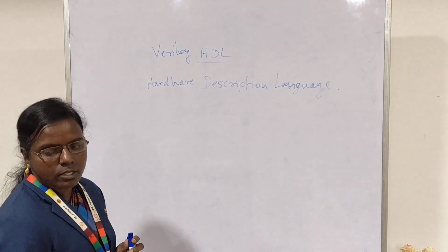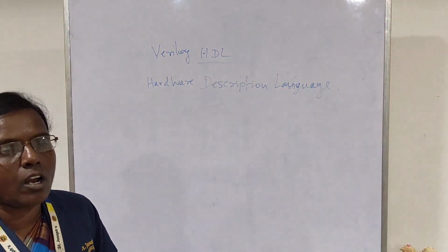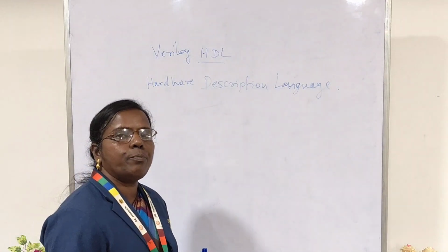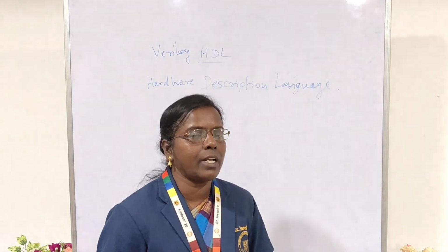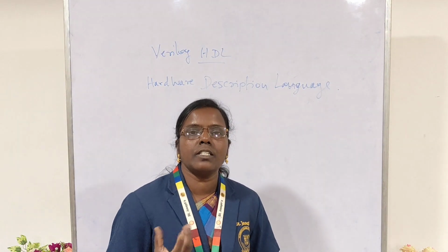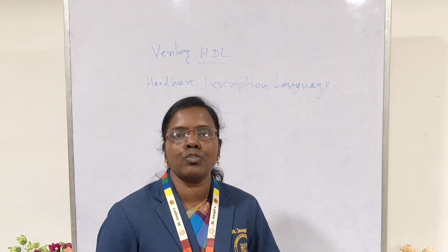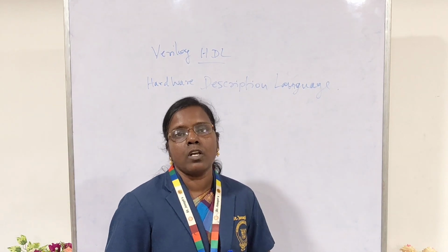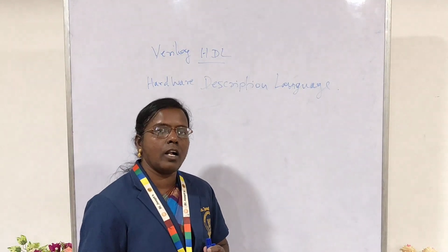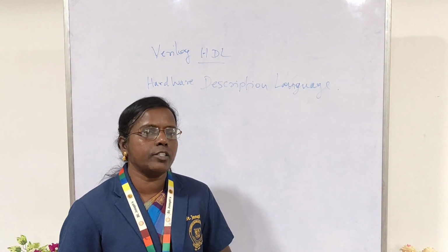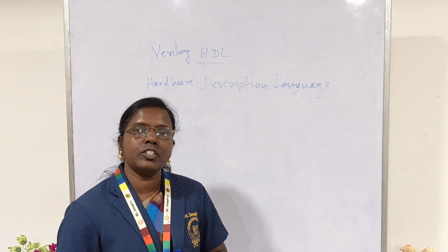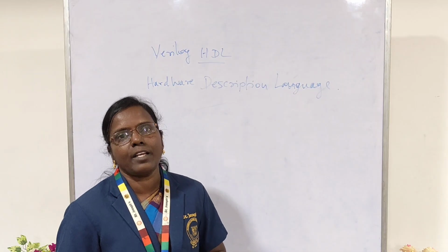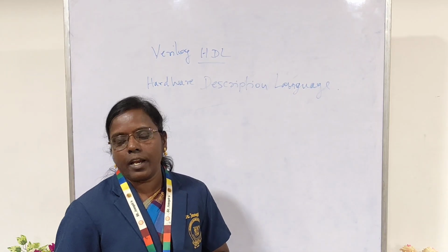Module is the keyword used in Verilog. Verilog has been derived from the C programming language, and most of the syntax used to represent keywords, identifiers and statements is also incorporated in Verilog HDL. Verilog HDL has been standardized by the IEEE association.